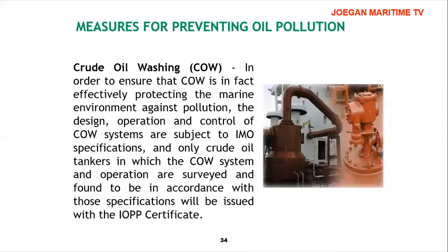Crude oil washing. In order to ensure that crude oil washing is in fact effectively protecting the marine environment against pollution, the design, operation, and control of the COW system are subject to IMO specifications, and only crude oil tankers in which the COW system and operations are surveyed and found to be in accordance with those specifications will be issued with the IOPP certificate.